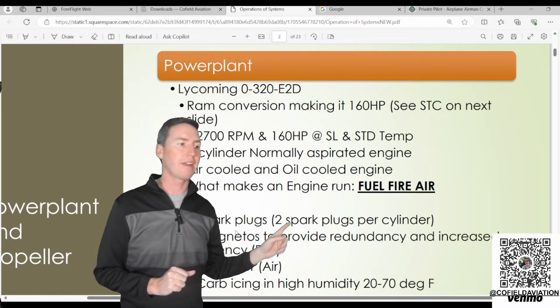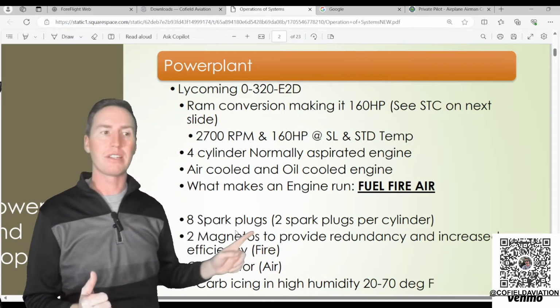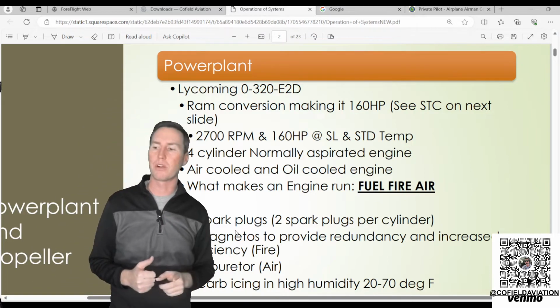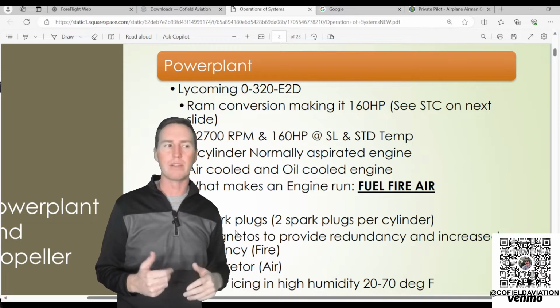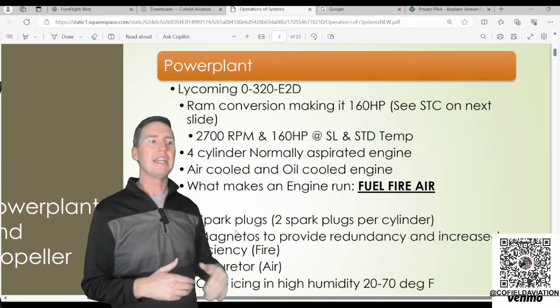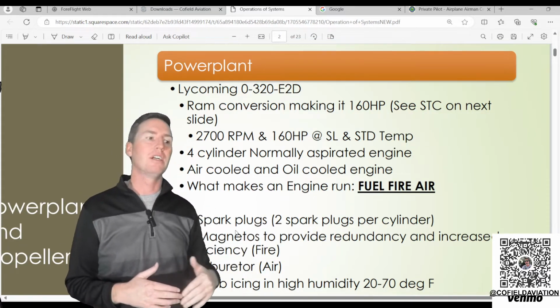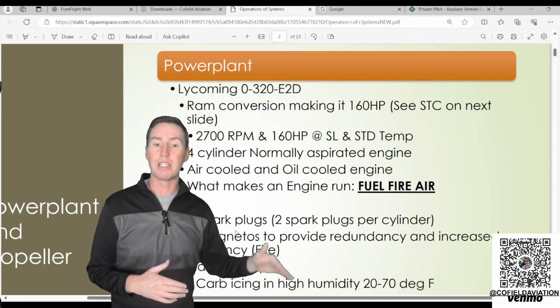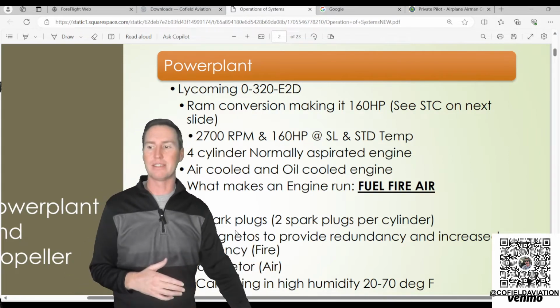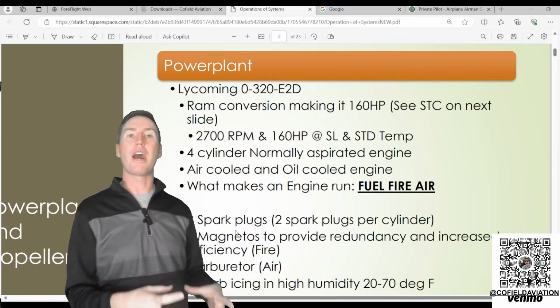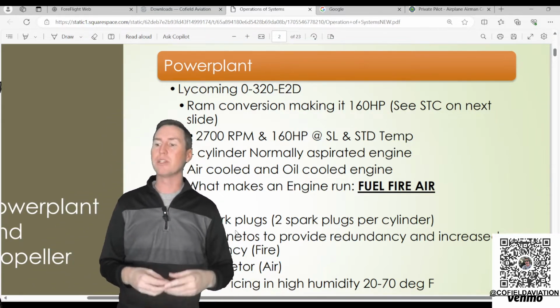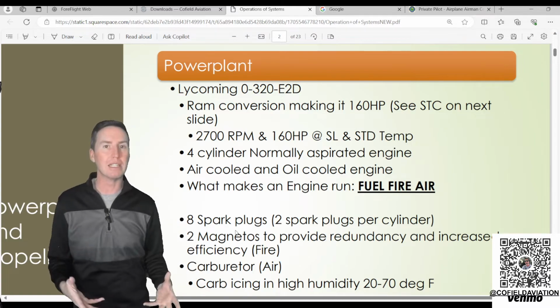A turbocharger can, for a Cirrus SR22T, which is the turbocharged one, it has a manifold pressure of 36, I believe, 36 inches. So it increases that pressure by 6 inches from sea level. So it's almost like the airplane thinks it's about minus 6,000 feet below sea level, which is a lot better pressure, which means a lot better performance.